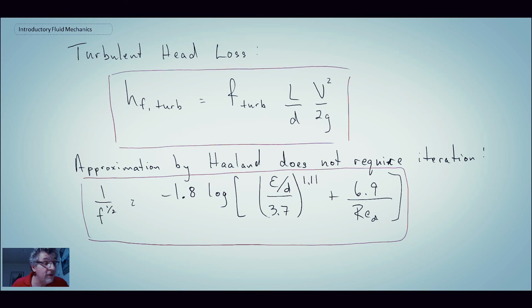So that concludes friction factor. We've looked at friction factor for laminar pipe flow, and we looked at it for turbulent pipe flow. We came up with different relationships, Colebrook-White, the analytic expression for laminar flow, and finally the Moody diagram. Those are all things that you can use when you're solving pipe flow problems in engineering.